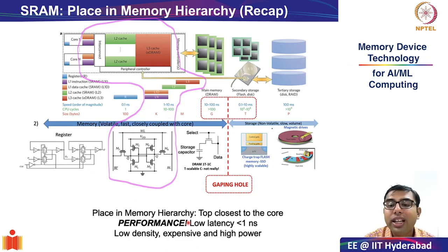Also, we saw that these SRAM cells are quite expensive when implemented along with logic cells. Why is this the case? This is because they are accommodated in the same footprint as your logic transistors. In essence, as we will see, they are made from the same transistor technology which constitutes your logic core.